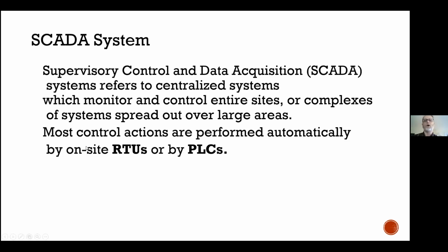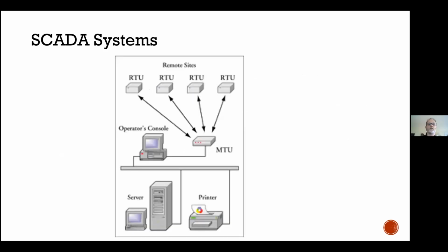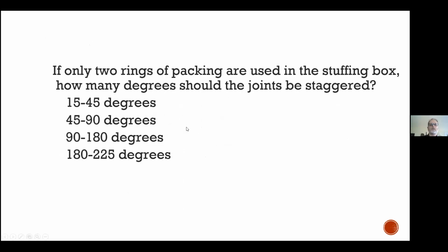But they now allow remote control as well as supervision of many sites simultaneously over large geographic areas. And typically the RTU, or remote terminal unit, or the programmable logic controllers are actually running the station. They sense the failure or fault or condition and report back, and gather historical data. That is how the system works. So here's an example of basically server, slave terminal, and then either through radio or telephone system or satellite, coming back in to let the operators know how the system is functioning.